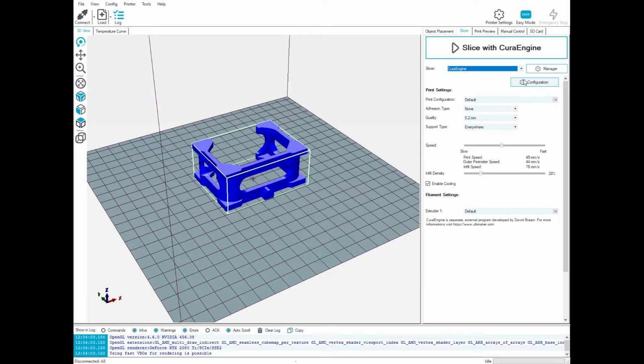I have a couple other videos. The advanced Repetier-Host video goes into some of those topics. My classic settings I run with is usually 2 or 3 outline passes just to make sure the 3D printing nozzle is good and primed. When the 3D printer starts, it usually doesn't print for the first few centimeters. So if you do a few outlines, not only is it helping confirm that your bed is level across the entire region of the printer to be printed on, it also helps make sure that the plastic is flowing and moving properly through the nozzle by the time you start printing any sort of important first layer material.